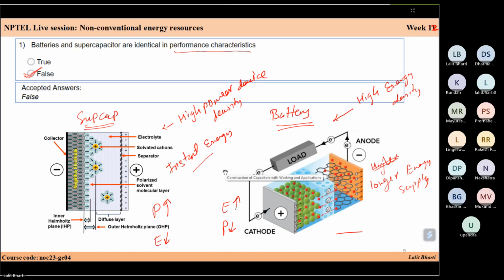But here, if you use an electrode material which has very high porosity, let's say you use graphene. Graphene itself has a very high specific surface area. If you see from the outside, you will see a simple 2D plane, so you can say this is an area of 1 by 1 meter. But as you look at the structure from the inside, you will see that at the surface these are not flat or plain. You have very deep pores inside.